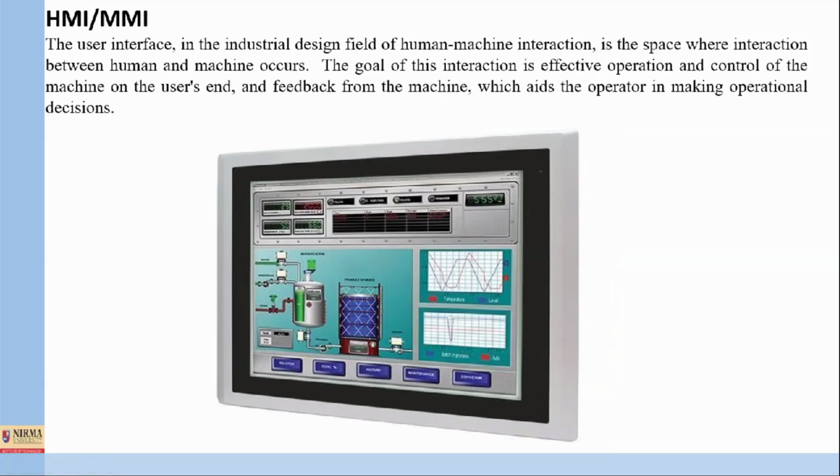And this is the human machine interface. Mostly when we go for an automation process, we use some software and interfacing devices which deal directly with the particular process. Some sensors in the process send the information, which is fed to the processor, and the processor pictures it through a graphical display. This is displayed over a panel, and the operator sits here and can control the temperature, air or fuel to that process simply by using this HMI, human machine interface.